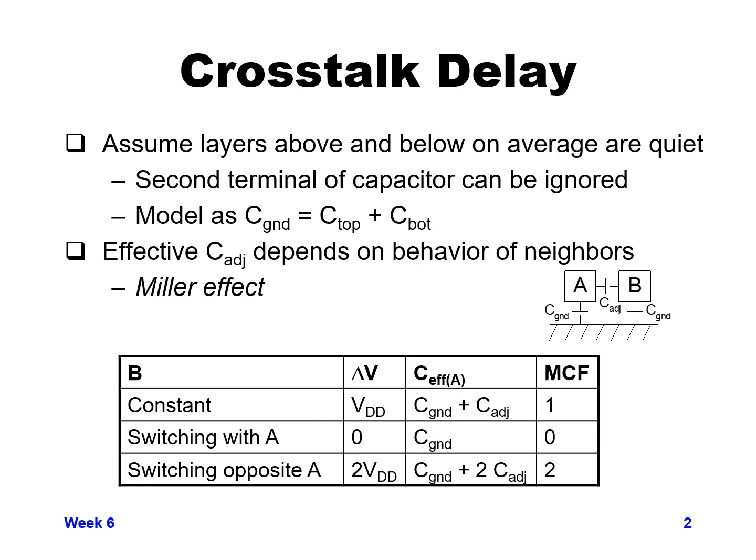So you have to calculate max delay based on an MCF of 2, and your min delay based on an MCF of 0. And that has to go into your timing tool and timing modeling, which makes your timing definitely more difficult to meet for both max delay and min delay when you have these effects along with other effects that make your max and min delay have vastly different times as well.